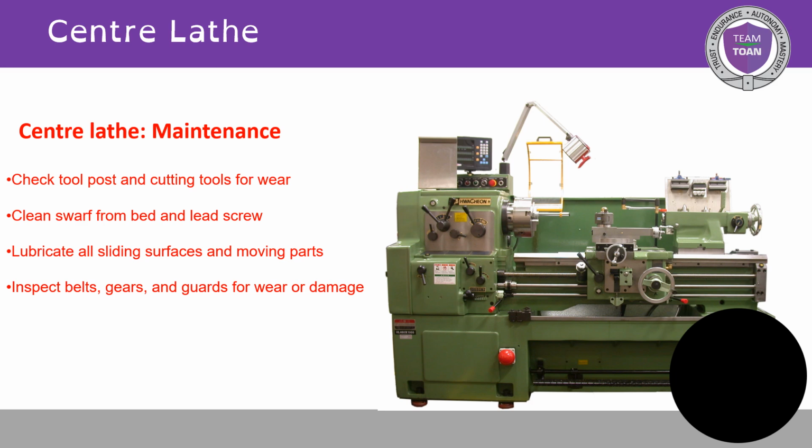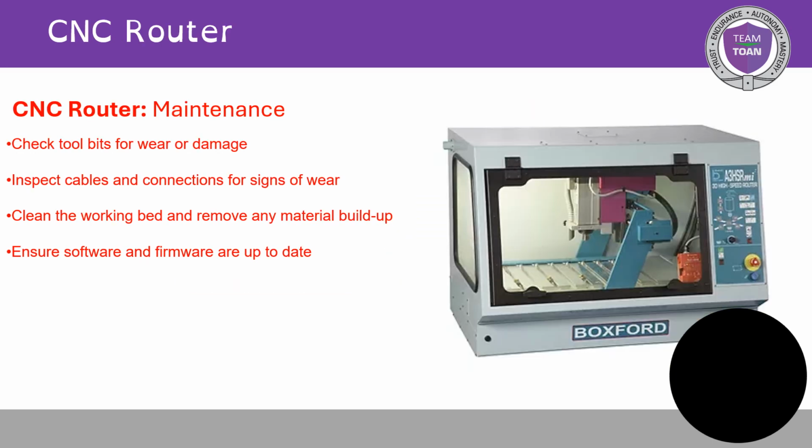On here we've got the center lathe, so check tool post and cutting tools for wear, clean swarf, so that's the debris from metal, from bed and lead screw, lubricate all sliding surfaces and moving parts, inspect belts, gears and guards of wear and damage.